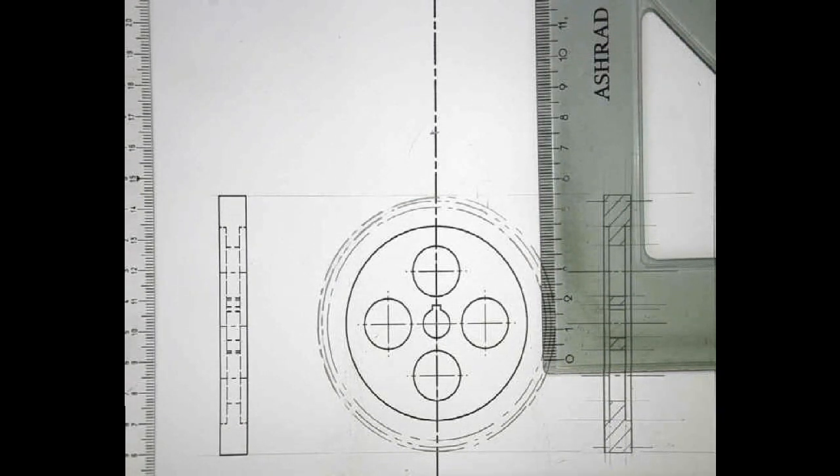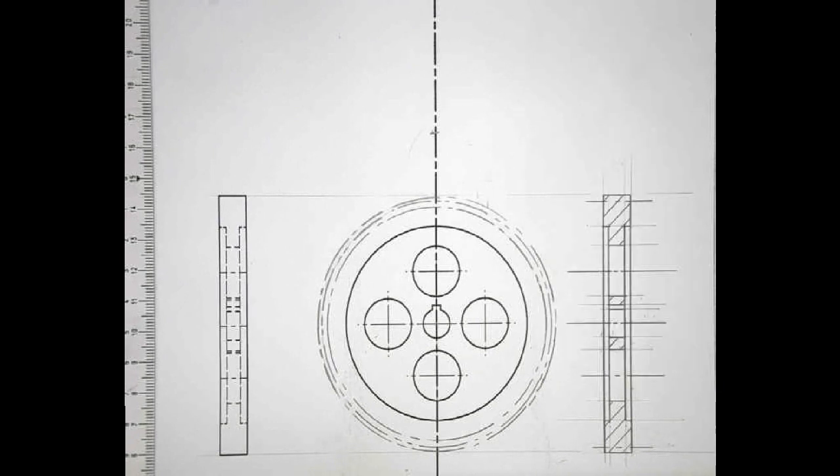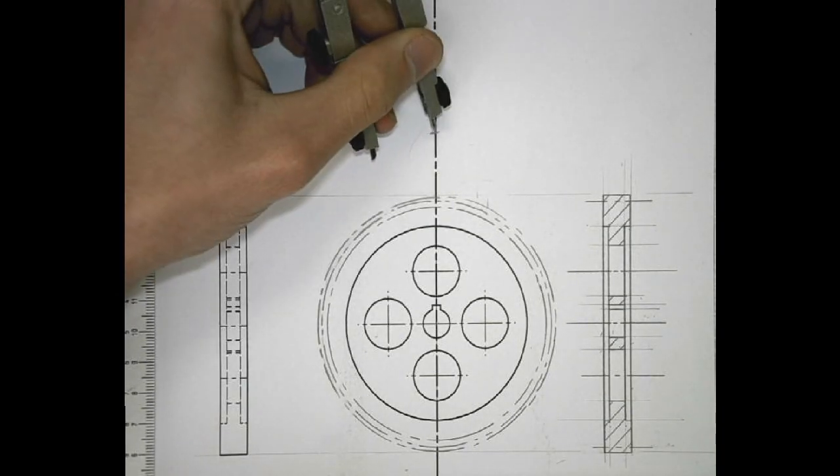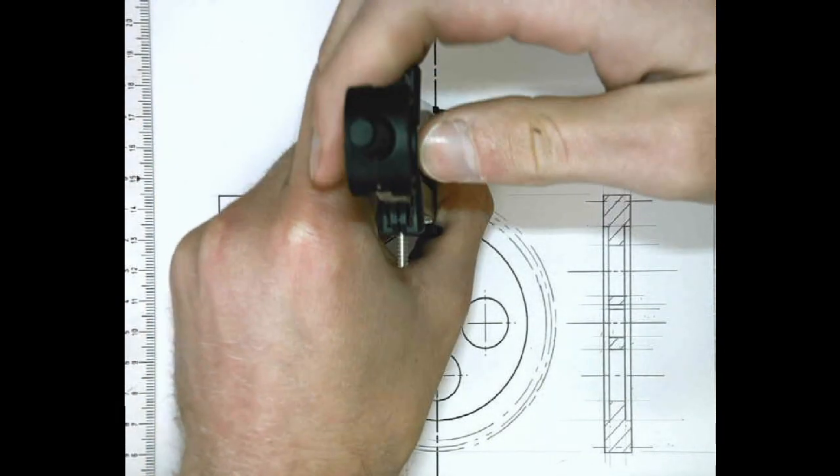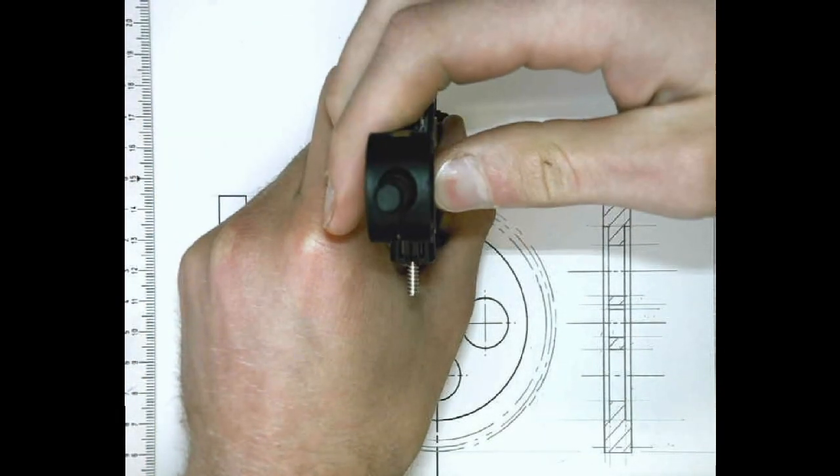Now, what we know about meshing gears, we can use to now construct the root, outer, and pitch circle diameter for our pinion gear without having to remeasure off, provided we've accurately drawn them on our gear system. So to get the outer diameter, it'll match up with the root diameter.